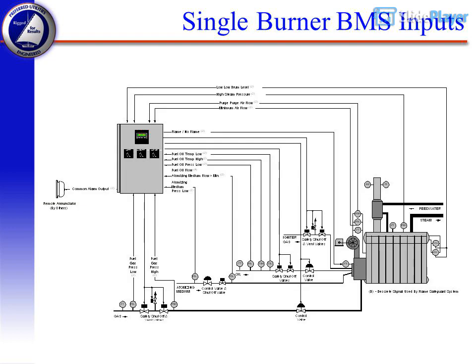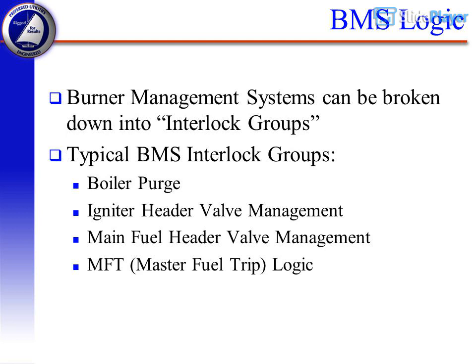Single burner BMS inputs. BMS logic. Burner management systems can be broken down into interlock groups. Typical BMS interlock groups: boiler purge, igniter header valve management, main fuel header valve management, and MFT (master fuel trip) logic.